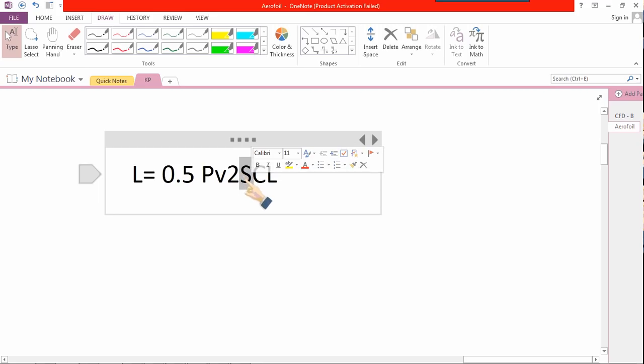So I am going to calculate the wetted surface area first of all. For that I need to make a special report called frontal area report. From that I will get this value, and after that in order to calculate lift I need density.